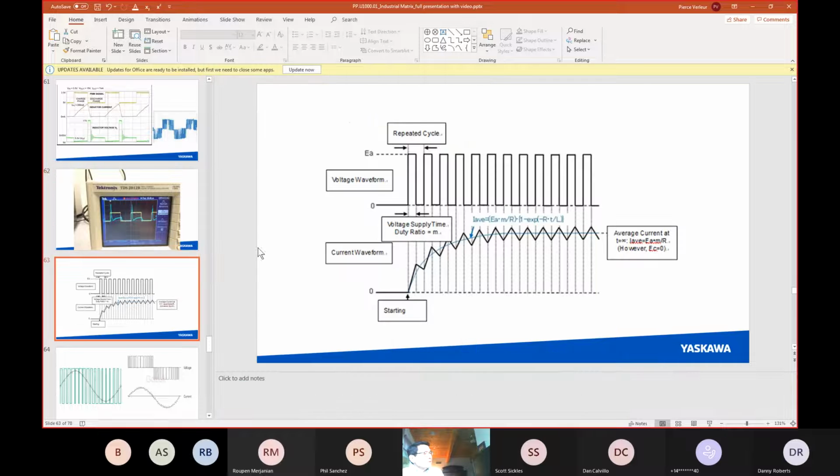So if we don't want to fall all the way back to 0 again, then we control our off time and we start the next pulse here, preventing a total degradation to 0 of the current, and we continue on our path up on the first half of the sine wave. Are there any questions on that?